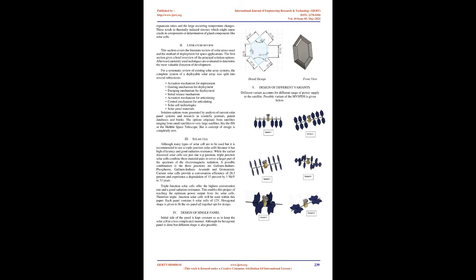Image of basic deployable structure. However, the concern herein is purely structural design and its deployment, and, as such, only relevant metrics will be considered, which include the operation of the solar array. This paper will present a preliminary structural design of a spacecraft that has less area with small packaged volume, and is sufficiently stiff. The developed design is based on a generic satellite mission and an orbit with an altitude of 400 kilometers. The satellite is assumed to be 3-axis stabilized.